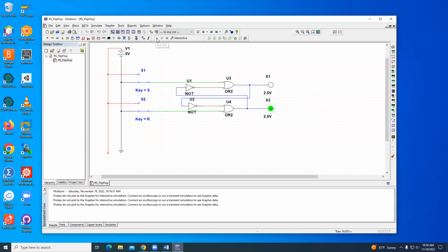If I turn it on in the hold state, it does this weird blinking thing. I didn't start in a good state, and all of my analysis of holding and so on relied on me being in a good state. So I get a very unusual behavior. Okay, that's what I wanted to show you here, a simple RS flip-flop.